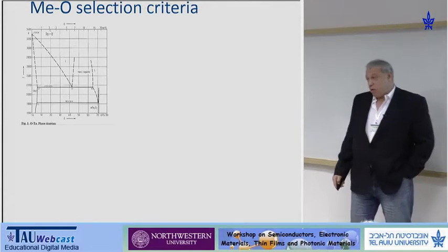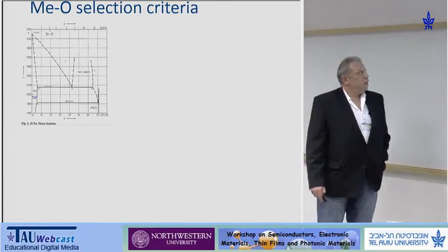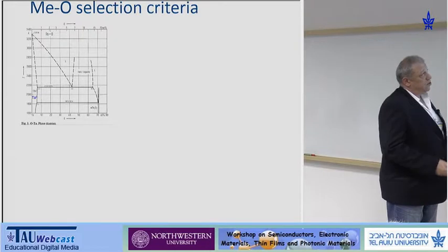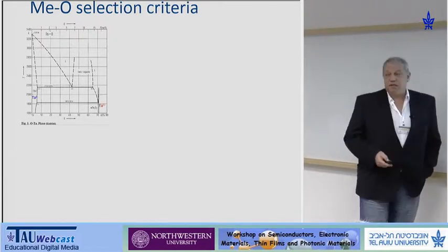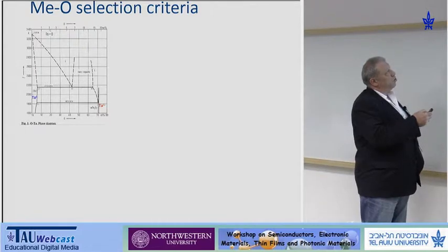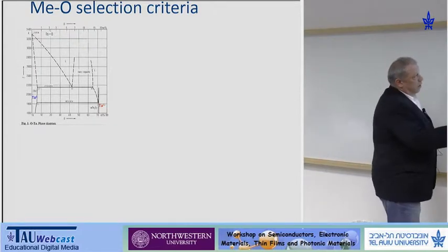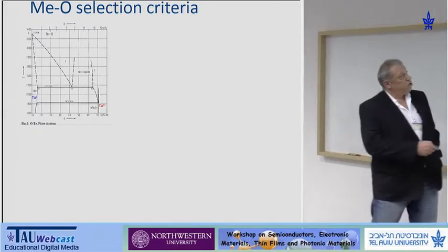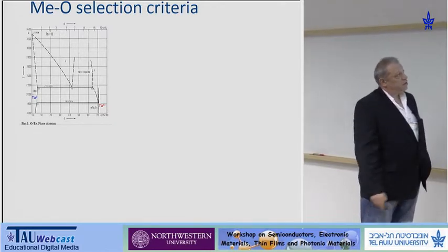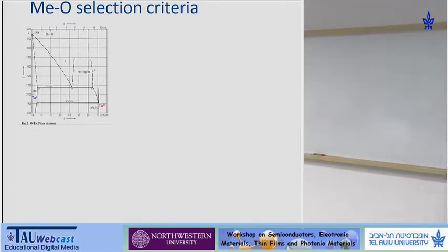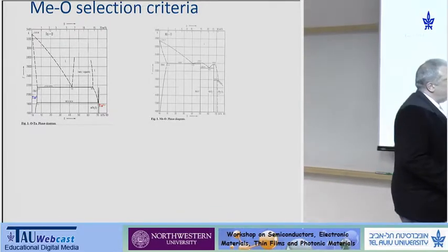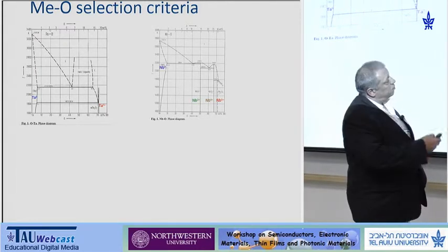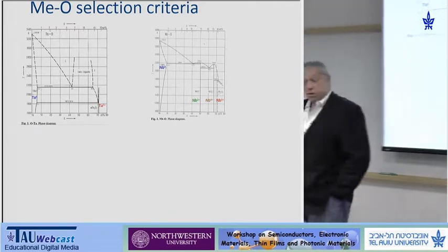So the materials I chose were tantalum oxide, and that's because, as I said, it's a workhorse, but more importantly, and you will see this related to our model, it has an extremely simple phase diagram. It has a solid solution of oxygen and tantalum on the one hand, and the terminal phase is the so-called alpha tantalum pentoxide, and that's it. So all this range is supposed to be just a mixture of these two phases. On the other hand, the other system I've selected was niobium oxide. Niobium oxide is more complicated because it also has intermediate phases, and we will see that it's material to the model I was talking about.